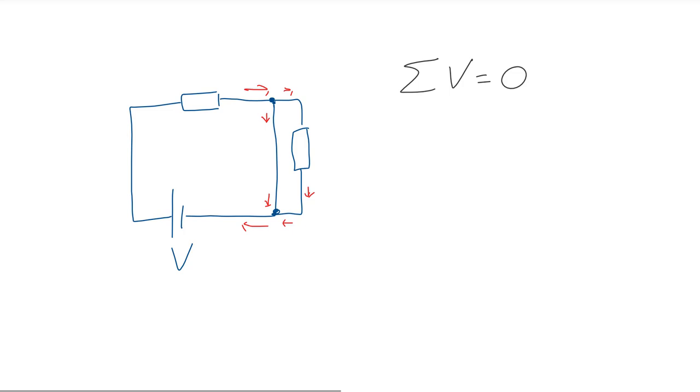What does this mean in terms of the Kirchhoff law? Well, remember we have two different loops here, and we know that the sum of the voltages around each loop must be zero. Therefore, since the only differences between these two loops are the two branches, the two parts of the wire on the right hand side, the voltages through both sections of those wires on the right must be the same. Therefore, the potential difference or the voltage on either branch on the right is equal to the other. This is what we get from using Kirchhoff's voltage law in this circuit. This came about, remember, by considering conservation of energy.